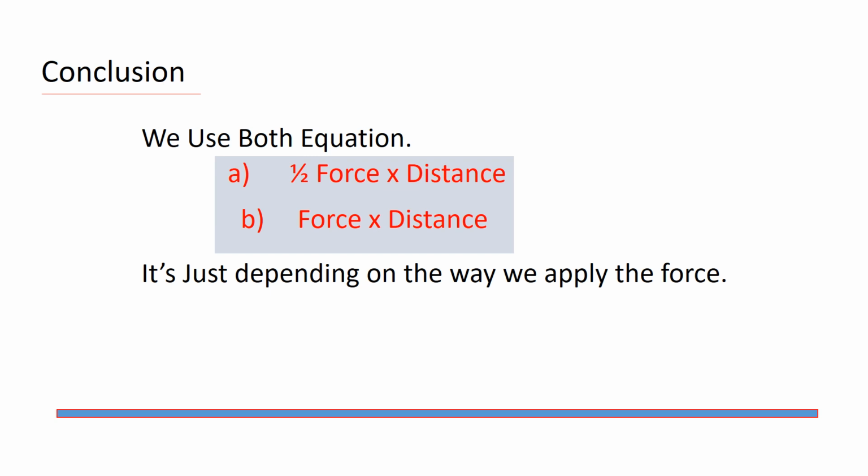A much more common type of work that is encountered in structural engineering is work done through the deformation of structural parts. This is part A of the calculations. If a load is gradually applied to the bar in tension, then the displacement of the right side of the bar also increases gradually, as we saw in the beginning of this video, in proportion to the increasing applied force.